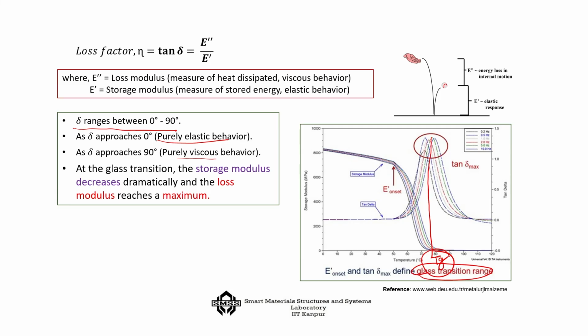So, what happens is that we can say, suppose the modulus of elasticity with respect to temperature theta varies in this way: at low temperature it is very high and at a high temperature it is low, and this is the Tg, okay. Now, with respect to the frequency omega, the value of E is just the reverse in nature.